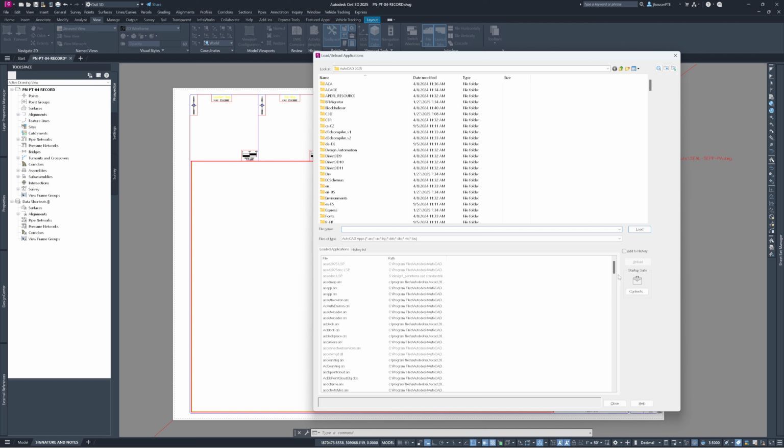See, I have my figure to poly also in there. They always load, and once they're in there, they load every time I open up AutoCAD. There are a couple other useful Lisp commands that we do have, but those two are the only ones I usually have loaded that come up every single time. And hopefully, if I configured your computer, I probably already loaded those. If not, we can easily get those back in there.